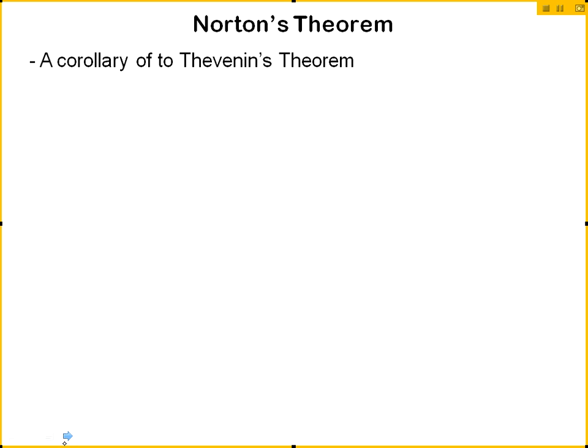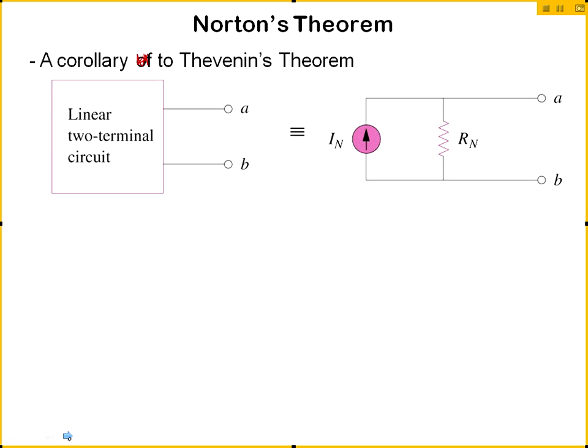Okay, Norton's theorem, okay? It's, in my opinion, kind of a cheap theorem. It's a corollary of, or to, either one's fine, to the Thevenin's theorem. Okay, what this says is as follows. Same thing, you have a system of elements, any number of voltage sources, any number of current sources, any number of resistors, in this complicated box, as seen by the terminals of the load AB. According to Mr. Norton, you can always replace it by the parallel combination of I Norton and R Norton.